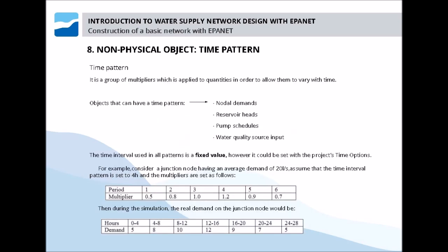Other non-physical objects which are very interesting for an EPANET simulation are time patterns. Time patterns are a group of multipliers which are applied to quantities in order to represent a variation over time. Node demands, reservoir heads, pump schedules, and water quality sources can have associated time patterns.